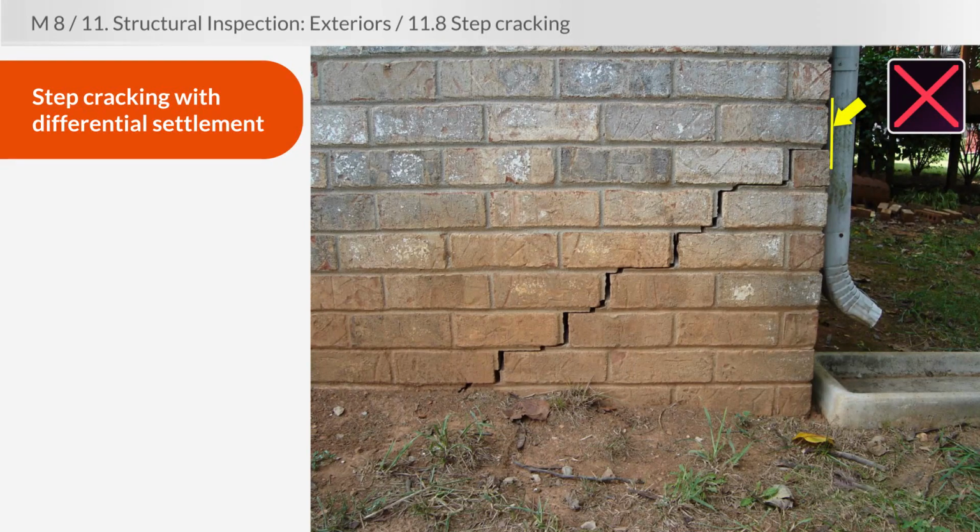The fact that the downspout just dumps into a splash block is probably not helping the situation. But in any case, this is probably a pretty good repair job for a foundation contractor, so that is who you would recommend for further review, a foundation contractor.